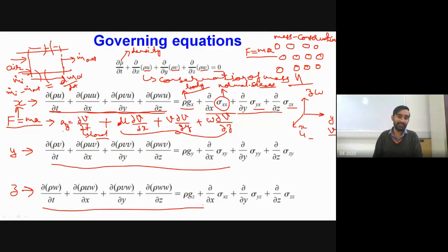So you can see that if we have to study the flow of fluid, how complicated the phenomenon is. We have a number of equations and a number of variables involved. The equations I have included in this slide are applicable for each and every type of fluid, because I have included the stress term in generalized form. If we have to apply this equation for a specific type of fluid medium, then we need to apply the corresponding formulation for stress.